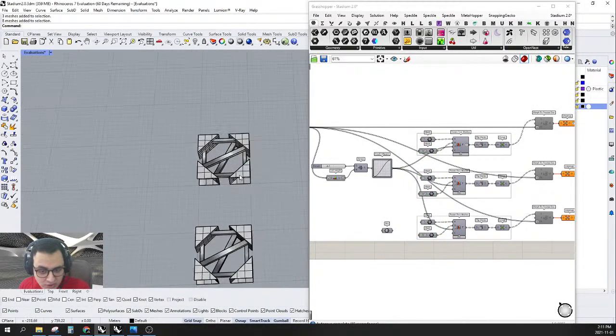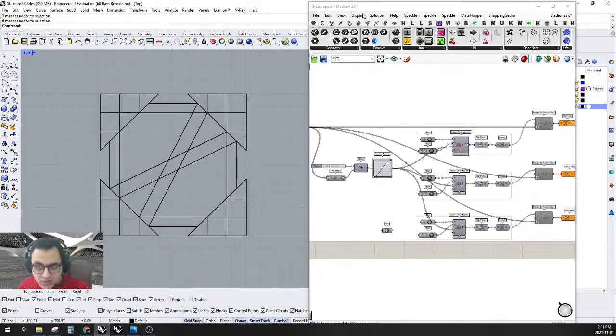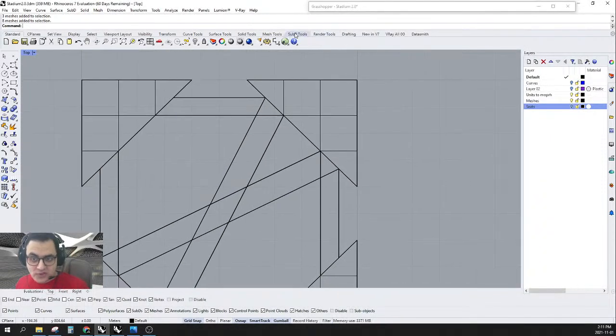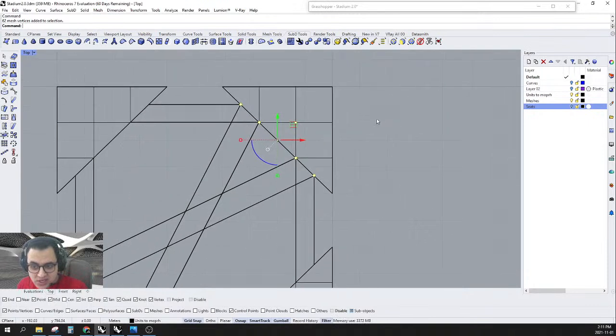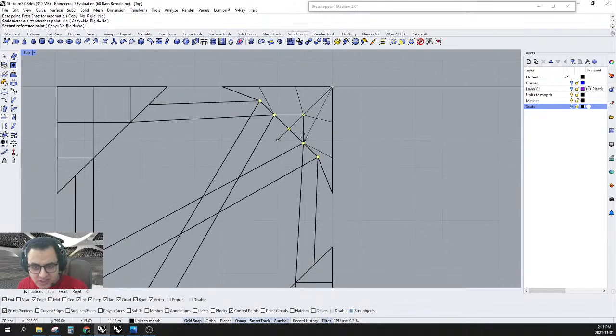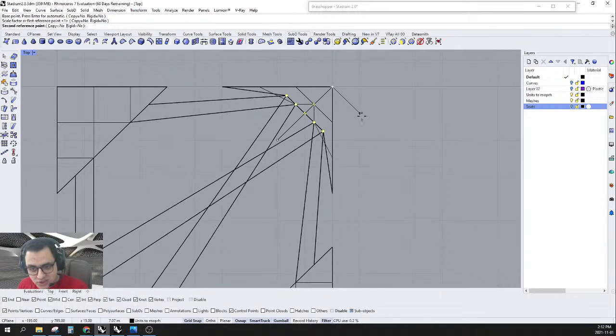And now I will edit this. Okay, let's go to the top and I will edit this. Let's go to the SubD and select the vertex. I will select only the vertex on the inside. Do not get any vertex from the outside, because that's one of the mistakes that we created last time. Let's ignore that. So this is the first thing. And scale 2D from here to here, and don't select anything in the middle in here, because it will be so hard, and the snapping will give you a hard time. Select anything from the outside, it's easier. So for instance, I will keep them all in here.